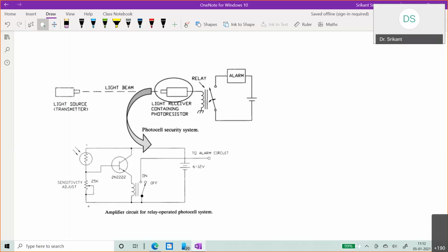So originally the transistor may be in the active mode or saturation mode. And once the light source is cut off, then this resistance becomes very large because of this diode, because of this resistor over here. And therefore this becomes open circuit. And if this is open circuit, then the entire voltage may drop across here and VB will become a small value and the transistor may go into cutoff. But there can be different mechanisms depending on how you connect the battery supply and all that. But that's the basic logic here.